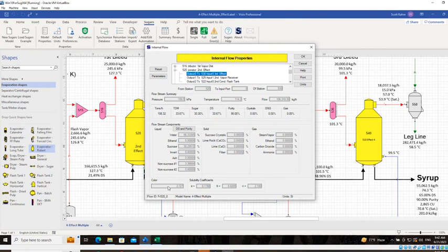One thing you could check is the overall screen resolution that you're viewing Sugars with. I know if the screen resolution is not large enough, it can cause some issues with how these windows display. I've seen that in other programs besides Sugars as well. So my suggestion would be to check your viewable screen resolution and maybe increase that if you can.